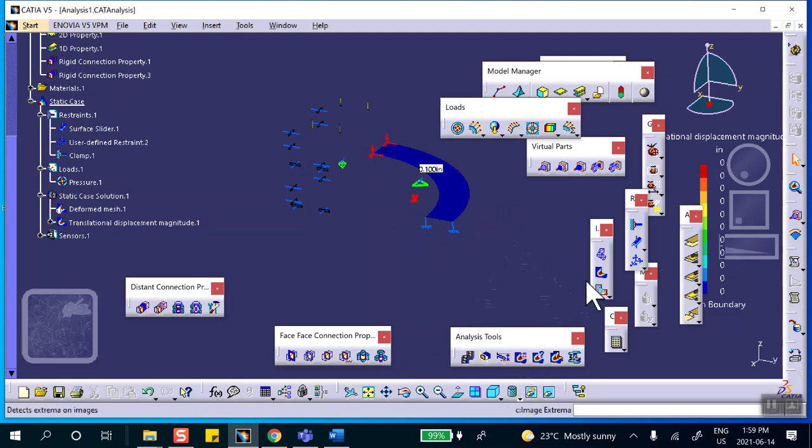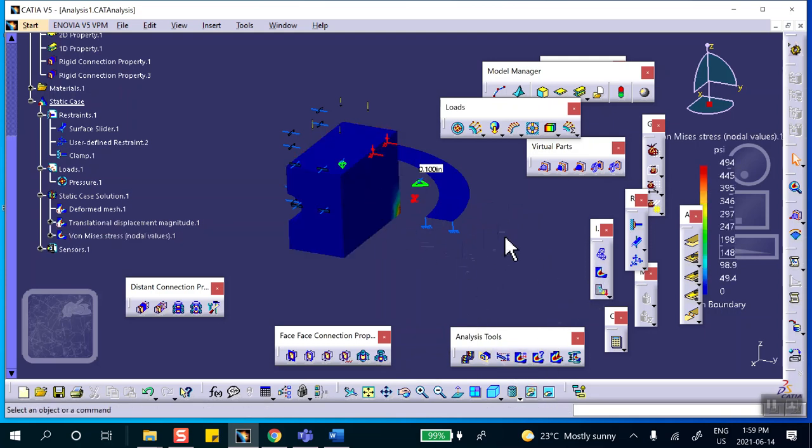And if you look at the stress distribution, the beam will have stress in it. Of course, you cannot plot the stresses in the beam. And yep, this shell does not go anywhere because the only thing that connects this to that solid object that moves is this beam, but that beam is coming to this point that is fixed in space. Okay, so this shell does not see any displacement at all. There's nothing wrong with it. This is the way it was.